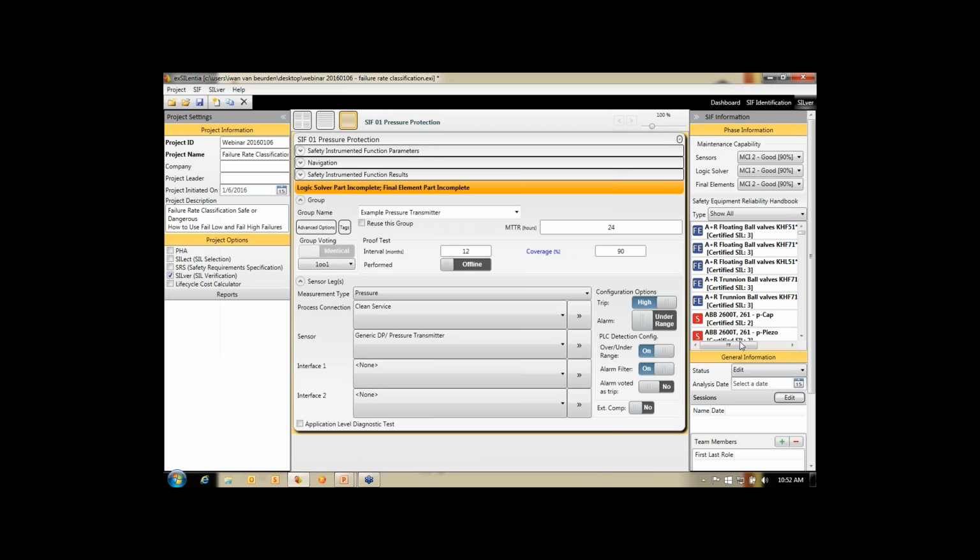And the reason for that is that in the definition of a safe failure in IEC 61508-2000, it was stated that any failure that is not dangerous is considered safe. And therefore, by definition, no effect failures needed to be included in the safe failure fraction calculation. IEC 61508-2010 corrected that. No effect failures are identified as a unique class of failures. And that was one of the comments that we as exSILentia submitted to the original version of the standard, that there's more failure modes than just simply safe and dangerous.